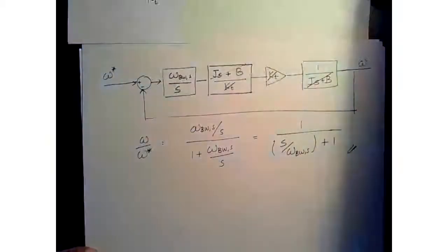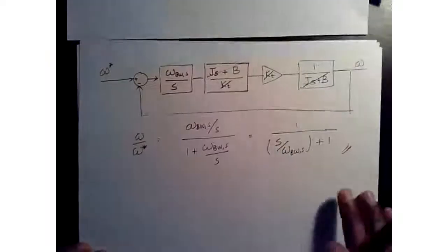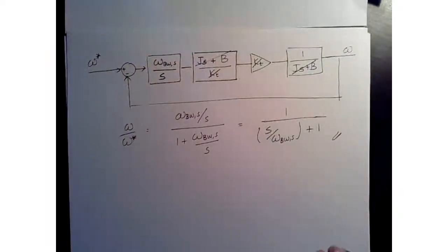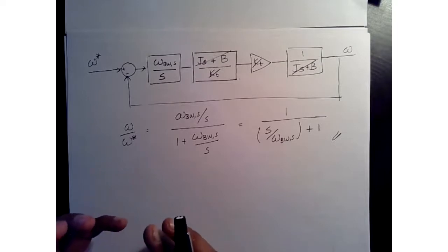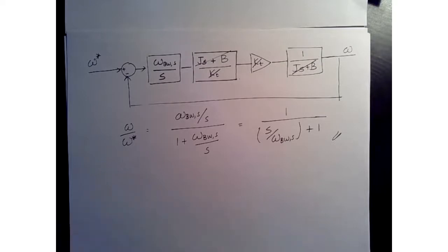Okay, so a very simple, very nice approach to design your controller gains without going into a lot of stability analysis. The primary reason that we can do that for a DC motor is because it's a first order system, both electrical and the mechanical independently. We can easily cancel the pole out and design a simple PI controller to achieve the control operation that we expect.